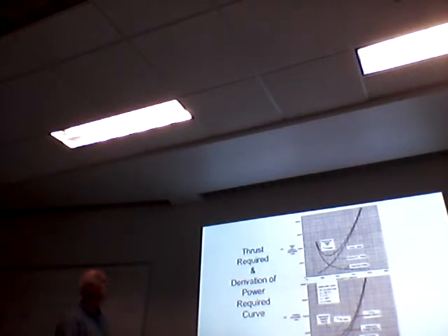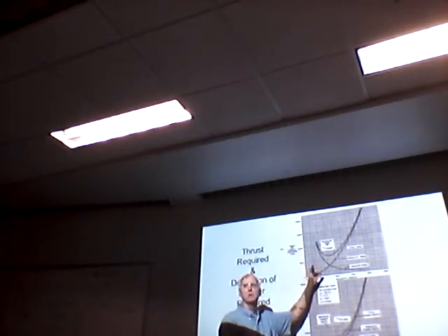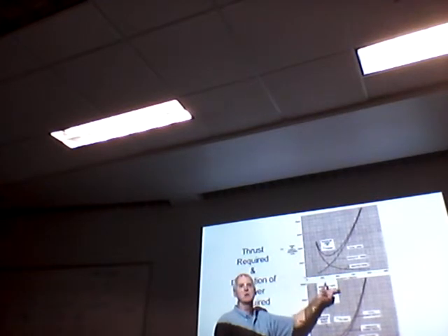We're going to have to dig that one out. I might have to pull up that other set of slides. But recognize that for a prop aircraft, L over D max, or this min drag point, has different associative properties than it does up there. So we had glide speed or glide range and best endurance and all that kind of stuff. Well, it's different for the prop.